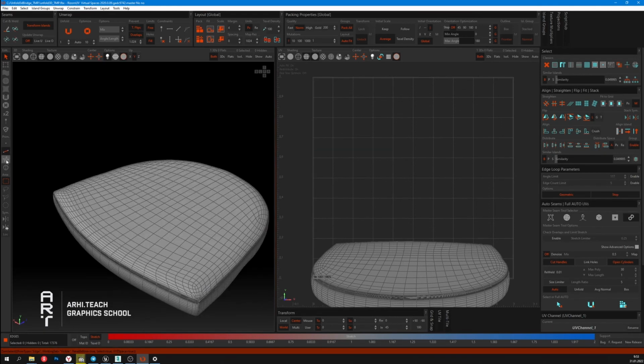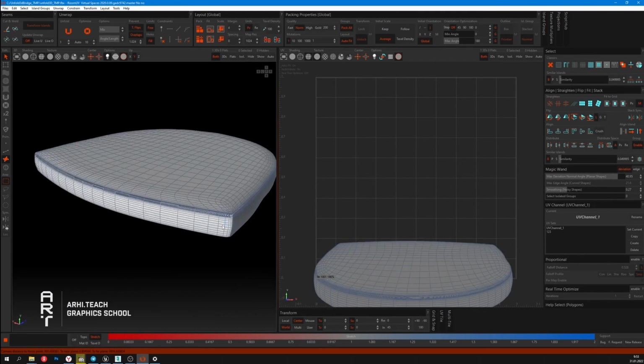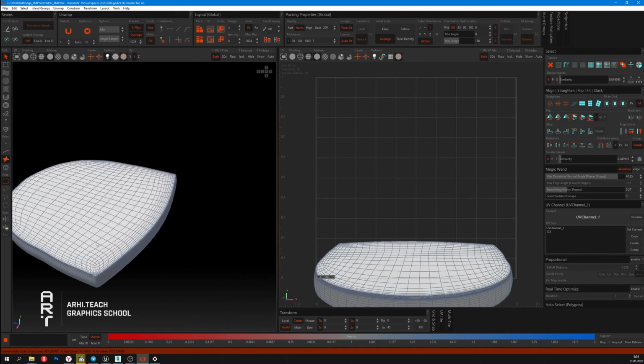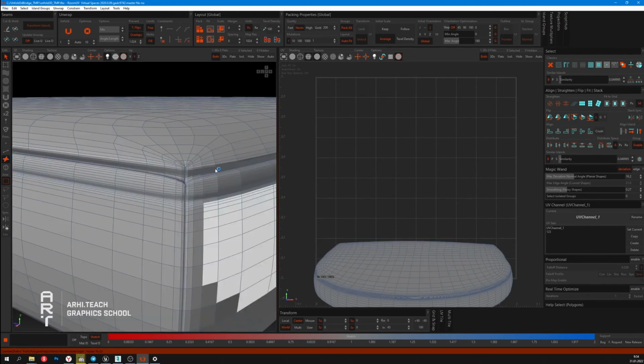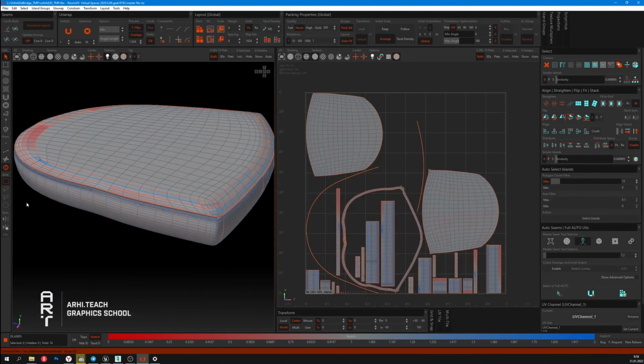Let's switch to the polygon tool. The polygon tool has several options of polygon selection. Activate them. We can see that the program suggests selecting the whole section. Using additional settings, we can select the size of this segment. Let's switch to the island tool. It has a number of functions that allow us to select islands according to the set parameters. For example, by the number of polygons.